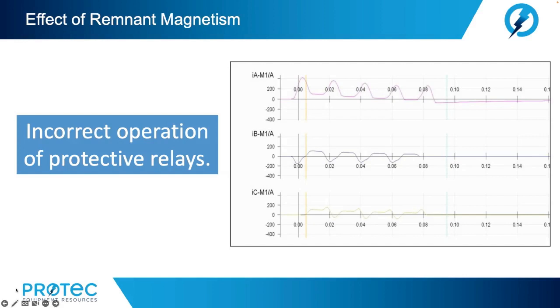The figure here shows a saturation where the inrush current was switched off after 5 cycles of transformer energization. The A-phase current exceeded 400 amps in the first half cycle, while the other 2 phases show great asymmetry, presence of higher harmonics in the current waveform. The consequence of this unnecessary relay operation is the need for another subsequent powering of a transformer, introducing another mechanical shock to the unit.